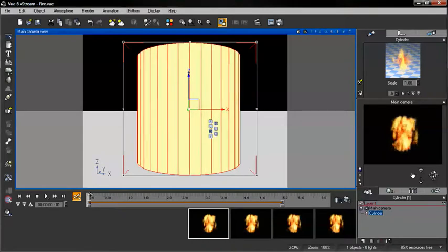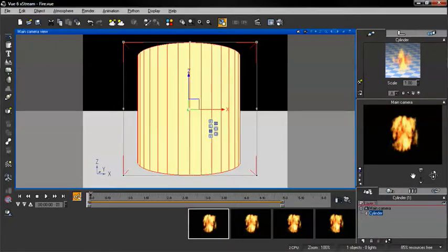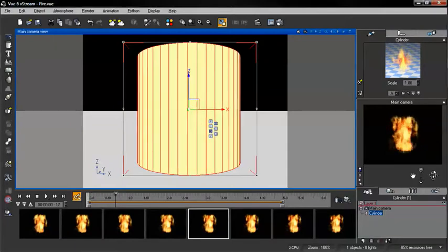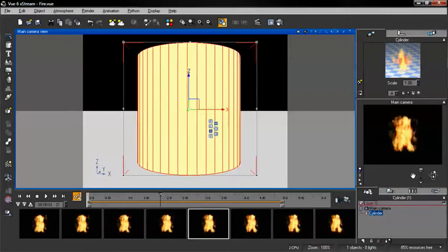Another thing to keep in mind is your preview might not be playing at the same speed as you actually have defined. So even though we have 5 seconds, our preview might actually take 7 seconds or longer to show. So sometimes the best preview is really just to render out the animation and take a look. You can use smaller settings if you need to, so it's a lot quicker.